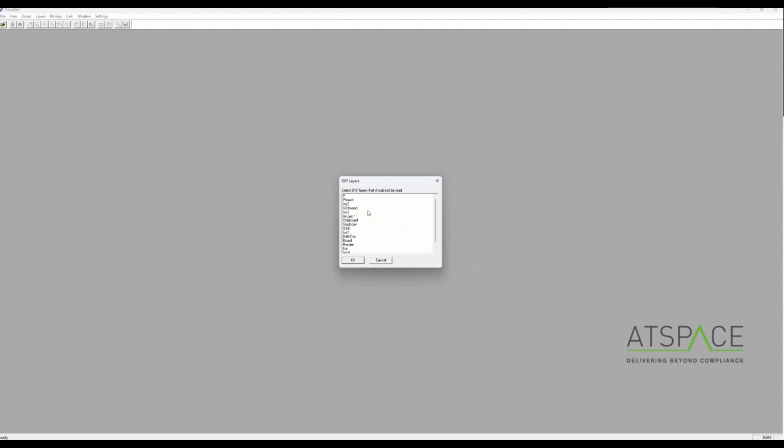When you open it, it gives you this box popping up here in case you wanted to exclude any of those polyline layers from your final model. In this case, we do want to exclude that P layer there, which is the original lines that were on the drawing, because we've gone over all of the ones we need to go over with all the different materials.